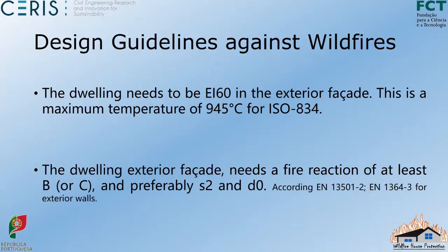The dwelling exterior facade needs to have a fire reaction of at least B or C, as I told you before, and preferably S2 and D0. Okay, once again, sorry for the typo. The European standard is not Part 2 but Part 1 for the fire reaction.